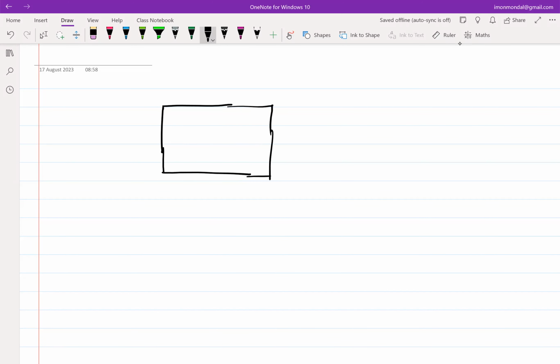We saw that if the stuff inside the box is a MOSFET, whose characteristics are well known, that is I1 equal to 0, and I2 is equal to beta by 2 times (V1 minus threshold voltage) whole square, or the linear current equation, right?